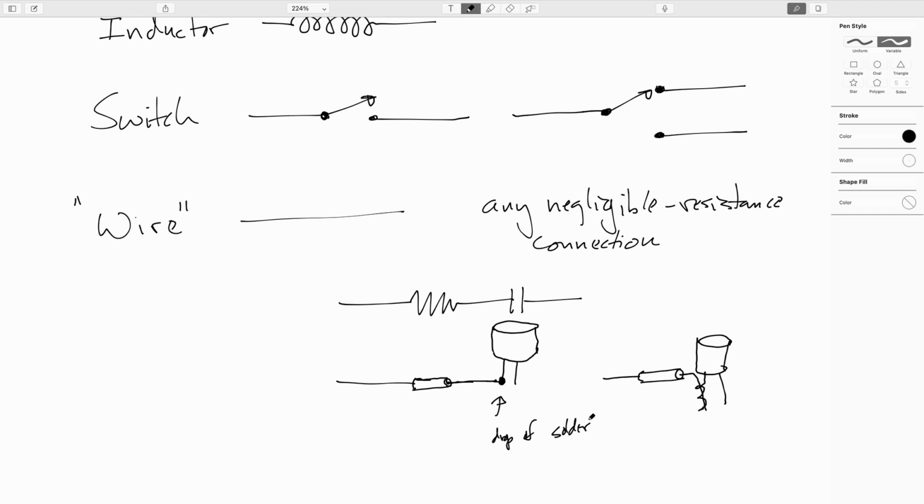In fact, one perfectly valid way to do it is that a lot of things are in metal chassis, and it's very common to hook up the negative terminal of a battery to that negative chassis, and then anything that needs to home run back to the battery, you just attach to the chassis wherever it's convenient. So these are all things that do get done. Alrighty.